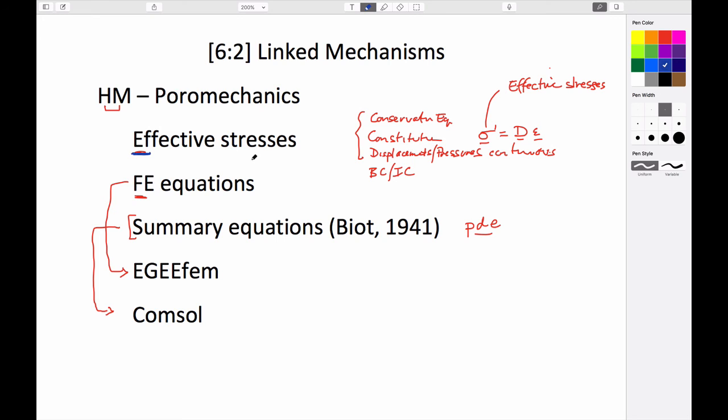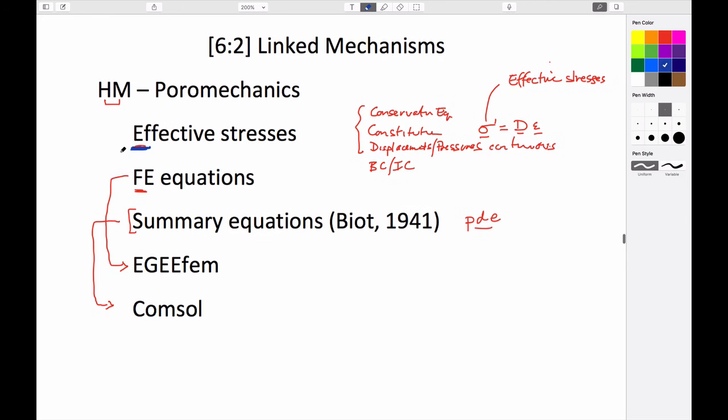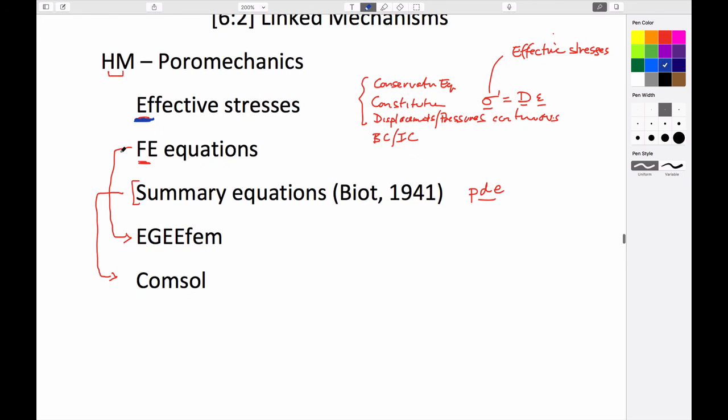So if we apply this to our system, we can get our finite element equation for solid mechanics written in terms of both fluid pressures and displacements. We can write an equation for the flow part, which is separate, and then we can arrange them so that they are loaded parallel from each other, but they don't interact. The way that they interact is through these other individual equations.